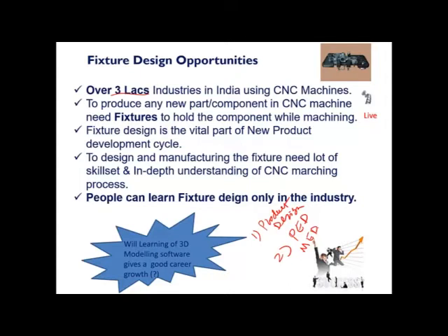You should know the basics, whether it is going to be a product design, you should know what casting elements you should give, whether it can be produced, in what way it can be manufactured, whether it is a GDC or a pressure die casting, in case of aluminum, injection molding, compression molding.